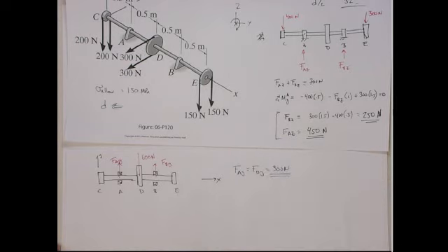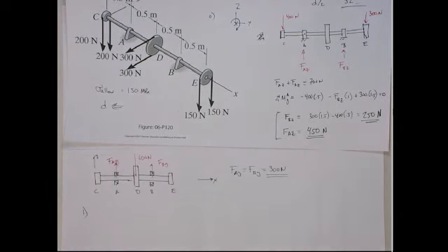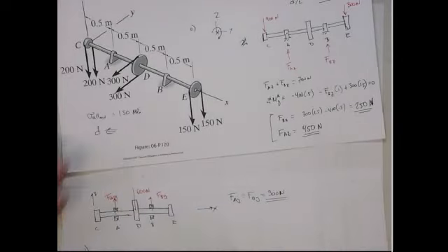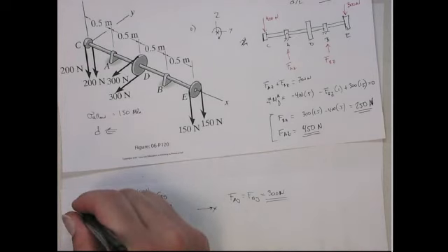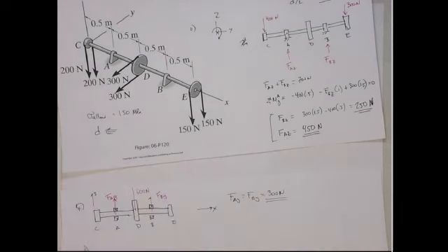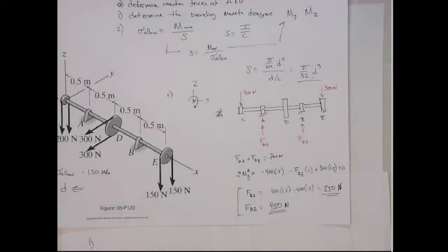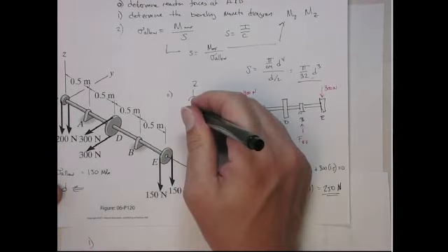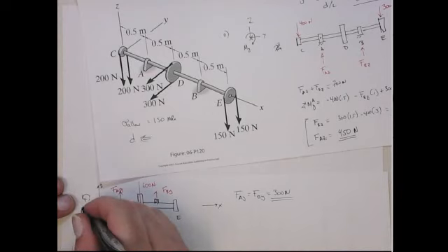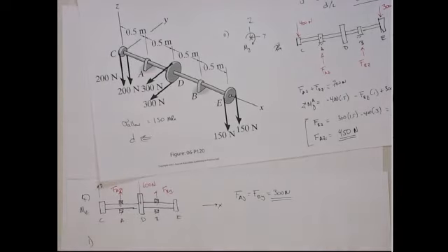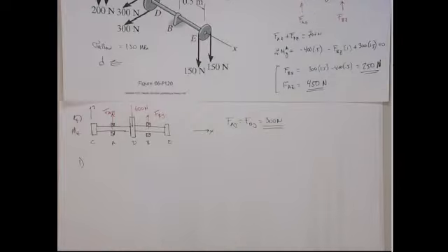Okay? So that's the 0th step I just did here, right? Step 0. Okay. Next, now that we know the forces, we can get the bending moment diagrams. And we'll have to get a bending moment diagram in both these planes. One in the XY plane, and in the XY plane, the positive bending moment is counterclockwise. And also in the xz plane, right? This one gives us the y moments, and this one gives us the z moments. All right? Okay, so let's do that now.